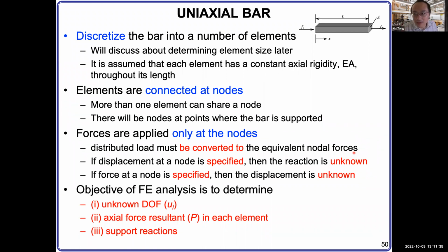By the way, if you study physics, you will know distributed force is actually everywhere, because we have gravity everywhere, right? So what we are talking about here as distributed force is more the externally applied, human-applied distributed force, like when you apply pressure there. Then those forces are larger than just the gravity. So when we deal with this, we will convert those distributed forces into concentrated forces.